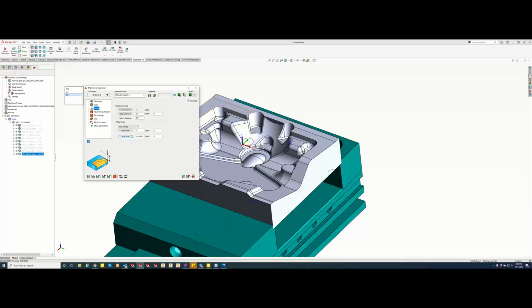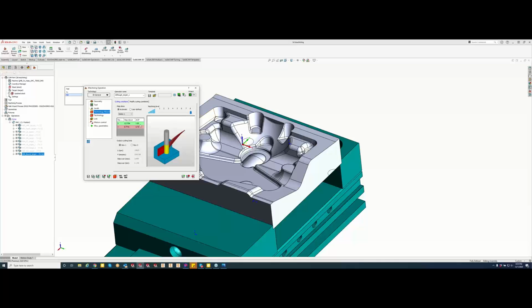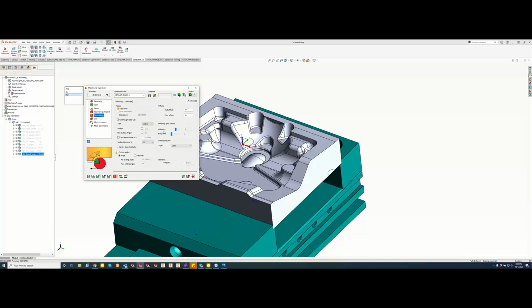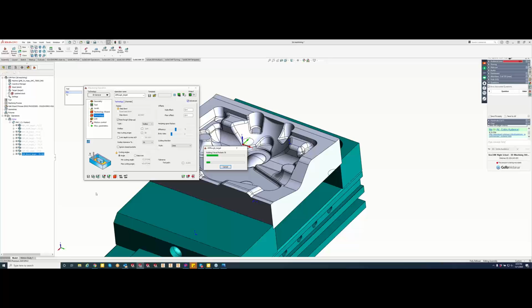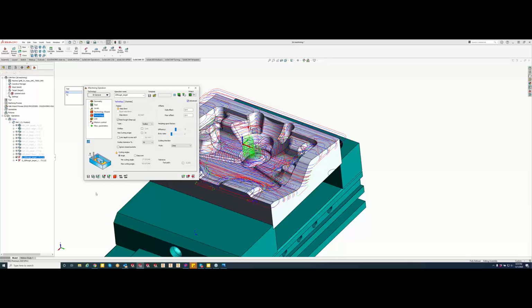Levels, it's already got our levels found since we're looking at the target model versus our stock, as well as our iMachining, so we can see that we're having 3 cuts that are very good, and 1 cut that is going to be taking a real thin slice, as well as we're doing a scallop. No, sorry guys, we're working in metric here. So we're doing a 1.32 millimeter scallop in there, but from right here, like I said before, grab a tool, save and calculate. And like I said before, what it's going to do is our scallop that we're looking for with that large tool, come back with that smaller tool and get any of the remaining stock there. Plus, I didn't have to figure out a feed and speed, which is really nice.